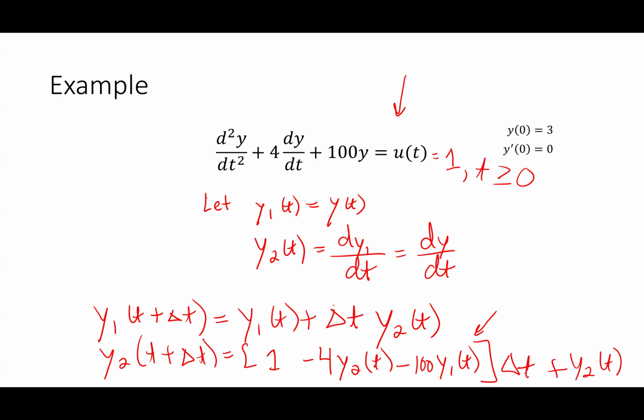All right. What is the steady state here? It's a constant. I don't think it'll be U of t. I think it'll be 1/100 U of t. Why do I know that? First of all, my input is a constant U of t. It's a constant 1 after t equals 0. So if my input is a constant, what's my output always have to be? Constant.